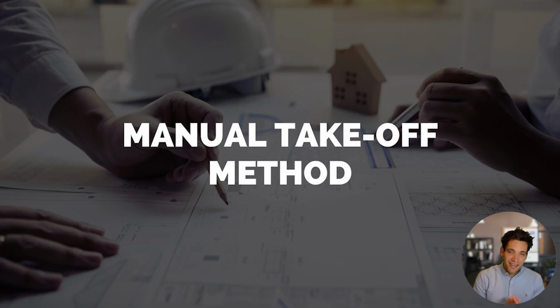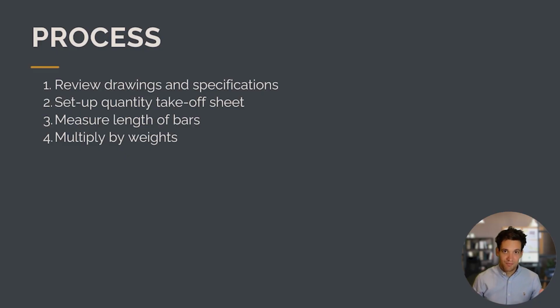Okay, so now let's get into the nitty-gritty of how to do a steel reinforcement takeoff. I'm going to start by talking about the manual takeoff method. So the general process, it's pretty self-explanatory. Review the drawings and specifications, set up a quantity takeoff sheet, and I'll use a specific type of Excel document that I'll put a link in the description of the video that you can download.